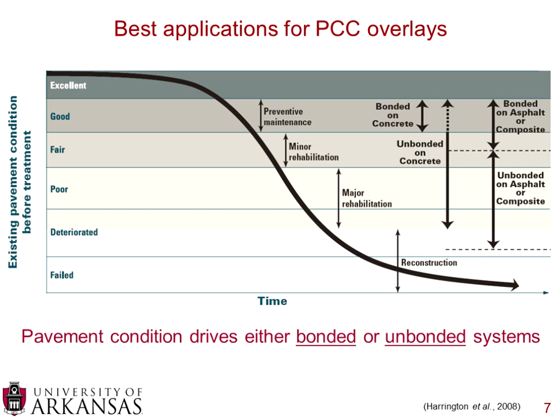This is another take on the slide image that we saw on slide 5 with the pavement condition rating. As time goes on, your pavement condition deteriorates. It starts at excellent and can go all the way down to fail. And here, what the National Concrete Pavement Technology Center came up with is just a little schematic to start talking about what sort of things need to be done. So as you're going down that curve, you go from preventative maintenance to minor rehabilitation to major rehabilitation all the way down to a full reconstruction.